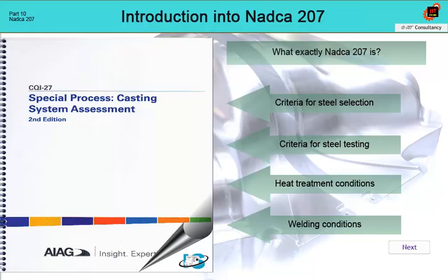In Table H, intended for high-pressure die casting plants, it is clearly specified that those who supply castings to the automotive industry are obliged to ensure that the design and manufacture of die casting tools is carried out according to specification NADCA 207. This changes the situation significantly, as it is no longer a free rule, but a mandatory one.